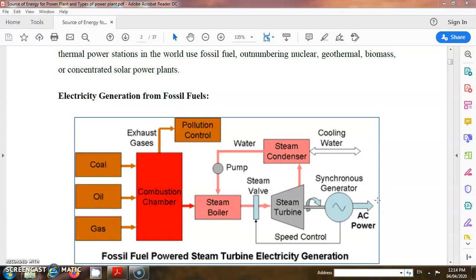The first is the downflow surface condenser, the second is the shell and tube type surface condenser, and the third, which is most important, is the center flow surface condenser. Again, the surface condenser is always coupled with one extra component, the cooling tower. The main function of the cooling tower is to supply cool water to the condenser shell passage. When the cooling water enters the condenser shell, it acts as a heat exchanger. It will help to exchange the